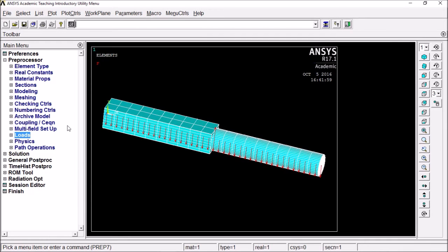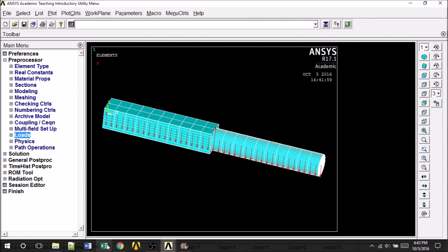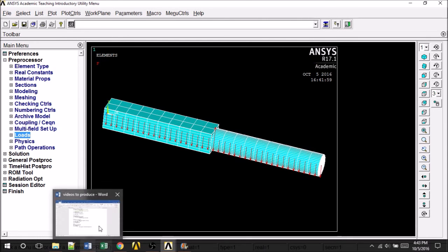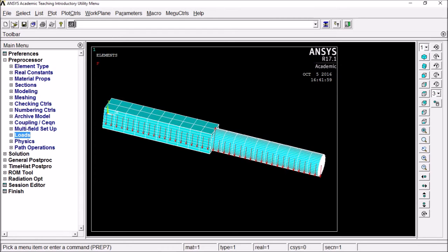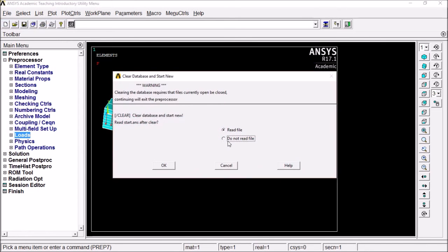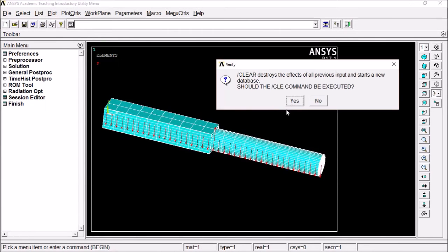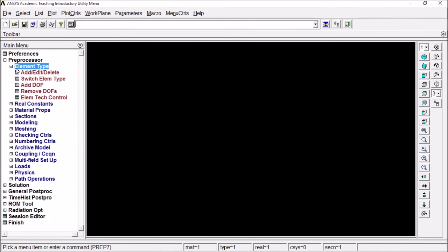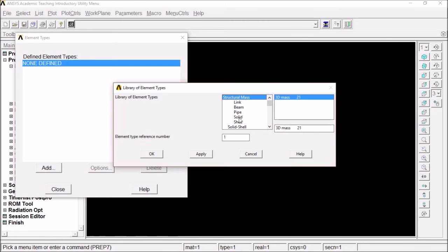And so the next thing you have to do is talk about putting displacements or constraints on a solid model. So give me a second here. I'm going to clear this code and bring up a solid model. I'm just going to make a simple volume. So let's see, clear and start new. Alright, quick element types here. I'm just going to use solid 185.